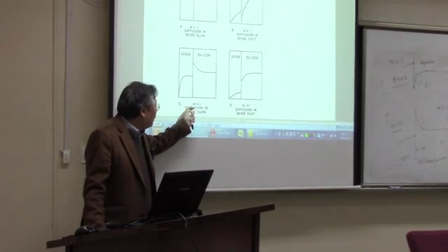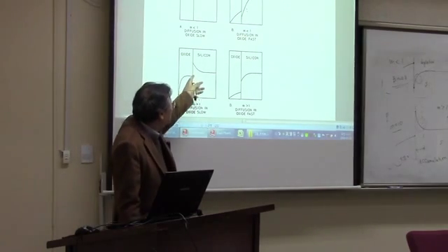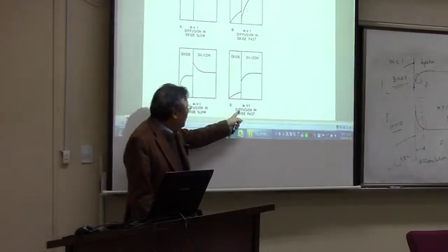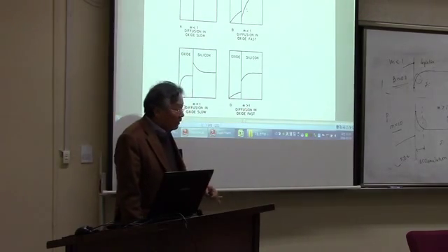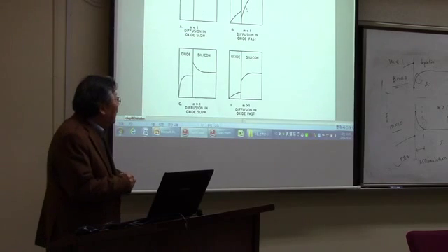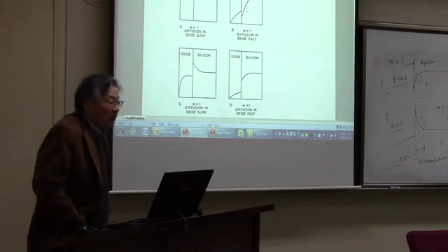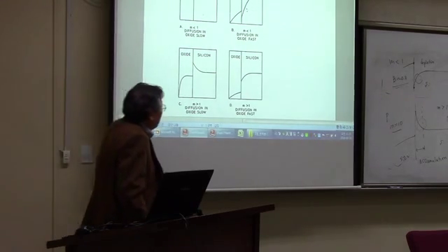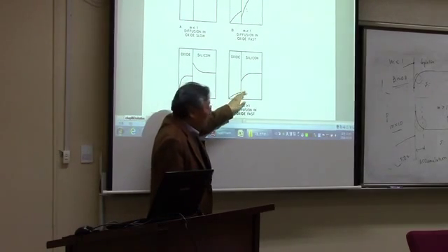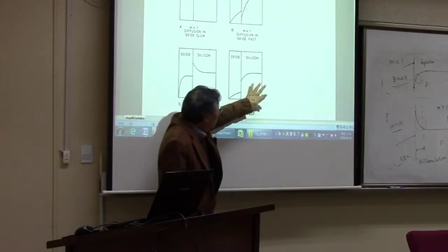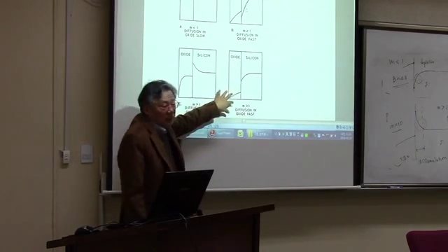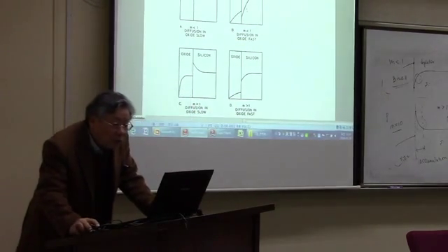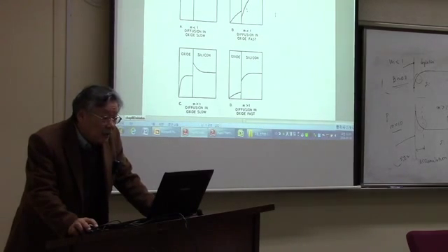In the case of phosphorus, arsenic, and any N-type dopant, we have the accumulation like this. And this is a special case that does not really happen in practice. But for example, in the gallium case, you have a very fast diffusion in the oxide, so that instead of accumulation, you're going to have depletion, because a large amount of dopant atoms is going to be deprived, you should say, incorporated into the oxide, if the diffusion process is very fast in the oxide.